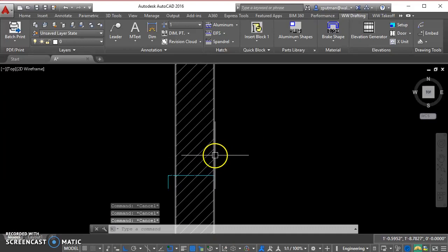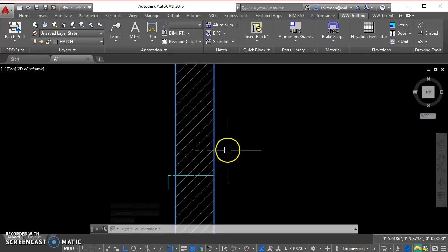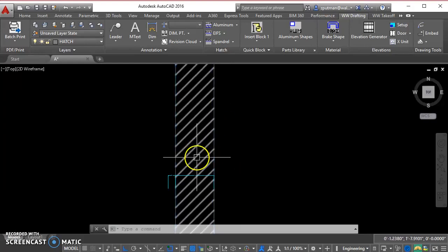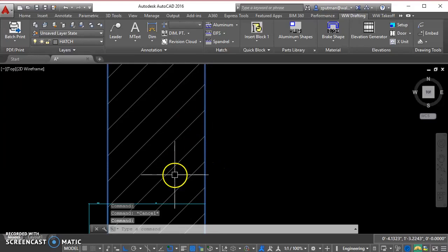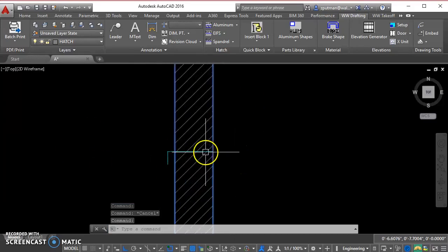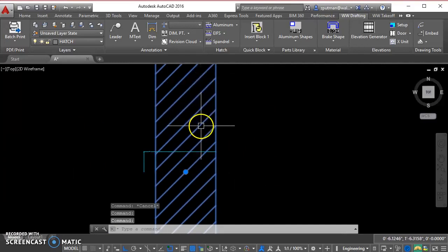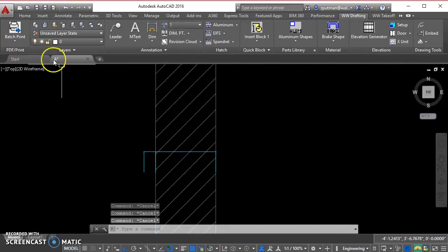So what this will do is, when you UPD or when you draw the glass patterns, it will insert this file at the origin specified by your glass tag, and it will trim this region to make it only cover where the glass is. And then because this is an associated hatch, it will also change. So it'll probably be best to see what this looks like, and you could just keep playing with this thing until you get it to look right. I've already messed with this a lot, so let's take a look at the unit drawings that I think I just outputted.